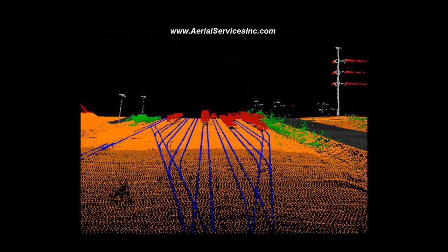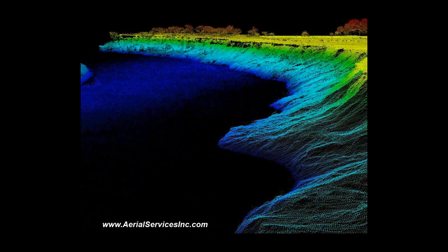Right. In the LiDAR, you get the point cloud of data, so you're able to take that point cloud and take it to bare earth. So if that's a need, then it's real important to be using the LiDAR. The RGB value of the stereo imagery is not going to be able to go through a canopy to see, say if you're mining a raw material and you want to see how to get it to a river faster and you're looking for tributaries, or if you needed to cut a helicopter pad. You're able to use the LiDAR in a bare earth model where in imagery that would be difficult to use.